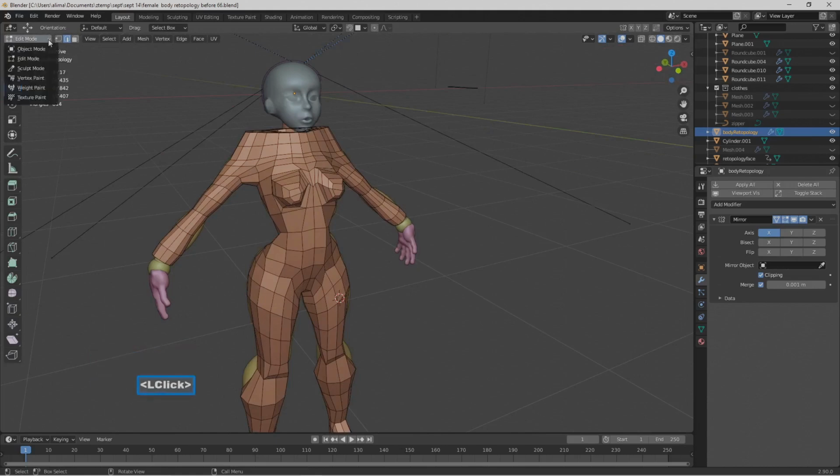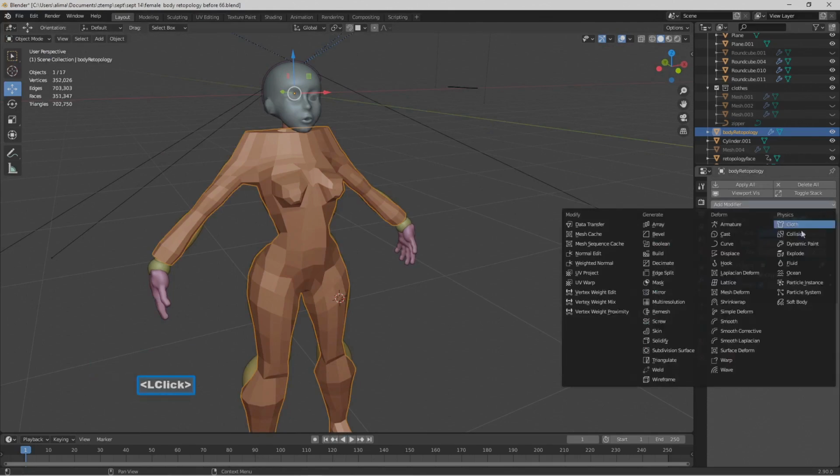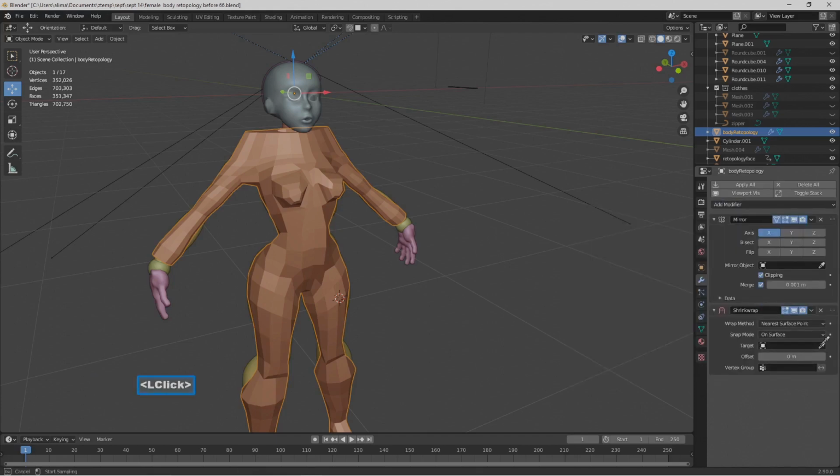That being said, we'll go to the upper left, go to object mode. We're on the wrench, which is our modifier panel. We'll select here, go to shrink wrap. We'll select the eyedropper. We can see where the eyedropper says mid torso, which gives us our sculpted mesh.